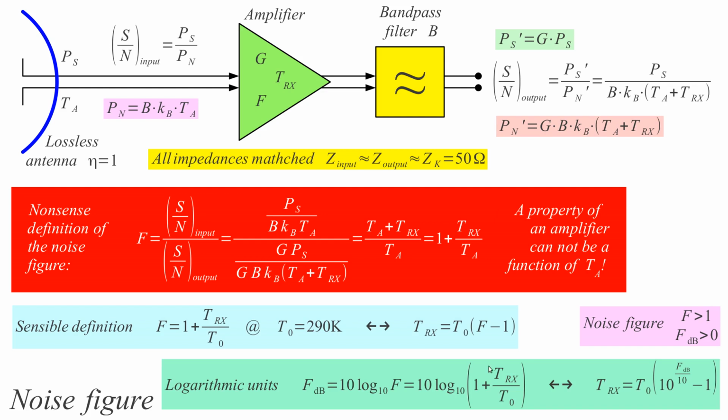As I said, the noise figure is only another way of expressing the noise temperature, as we have selected the value for the reference temperature T0, and this is fixed, selected, defined. This is our reference temperature. Then there is a one-to-one relationship between the noise temperature and noise figure, or vice versa, noise temperature calculated from noise figure in decibels.